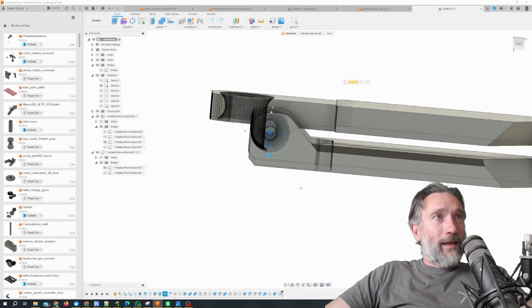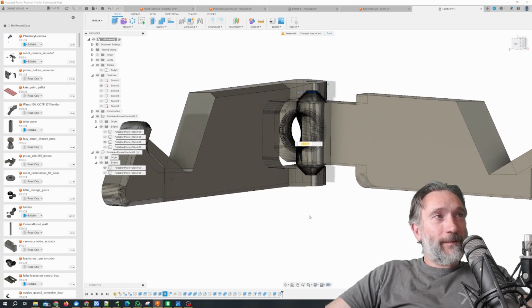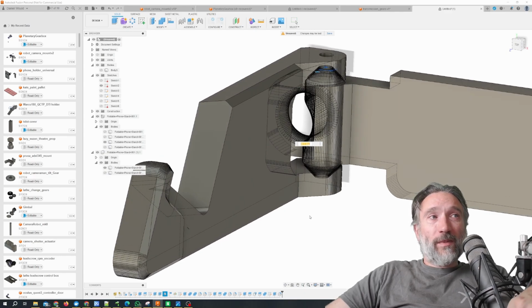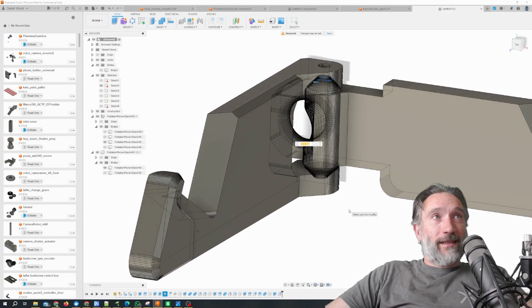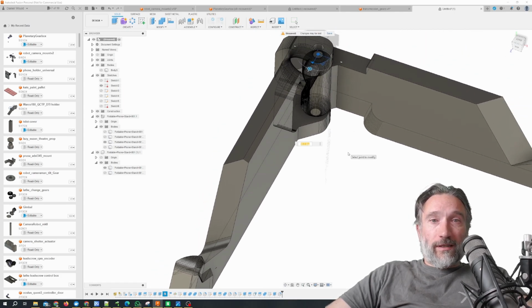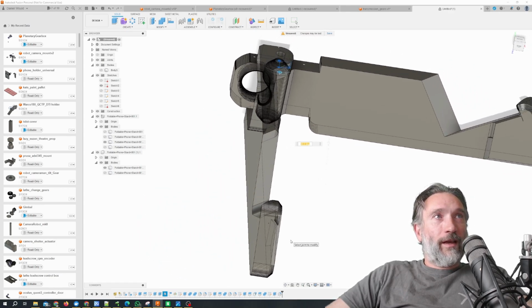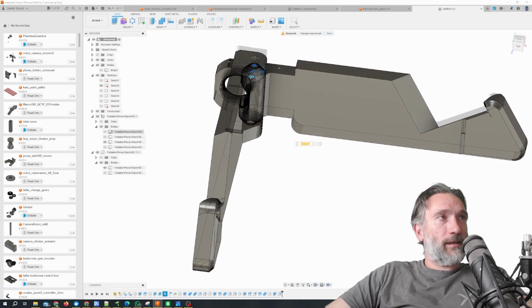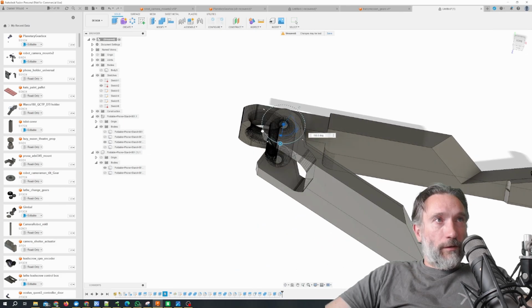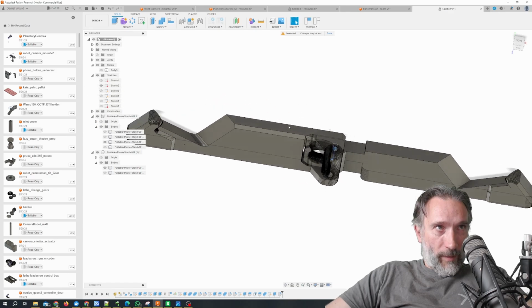So there you go, that was a bit of a long run through, longer than I intended, but we'll edit that a little bit. Some basic editing of an STL. The main trick being project the points of the original STL onto your sketch planes so that you have reference points to rebuild the bits of geometry that you need. Then you can kind of hack and slash your way through. It's useful to set up components for this kind of stuff where you can get it into the arrangement you actually need.